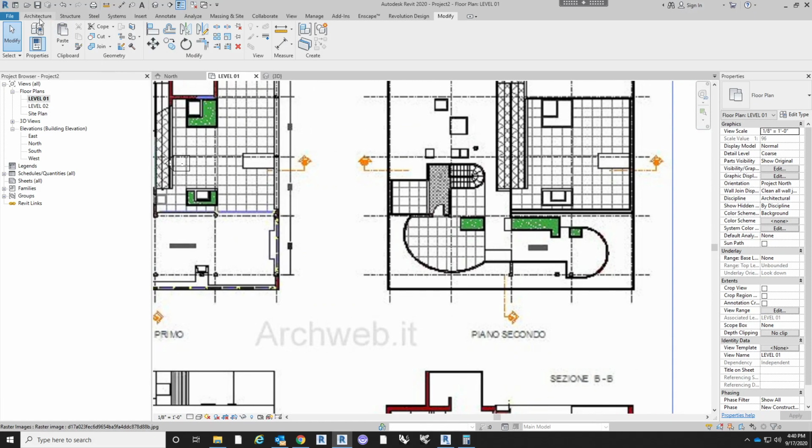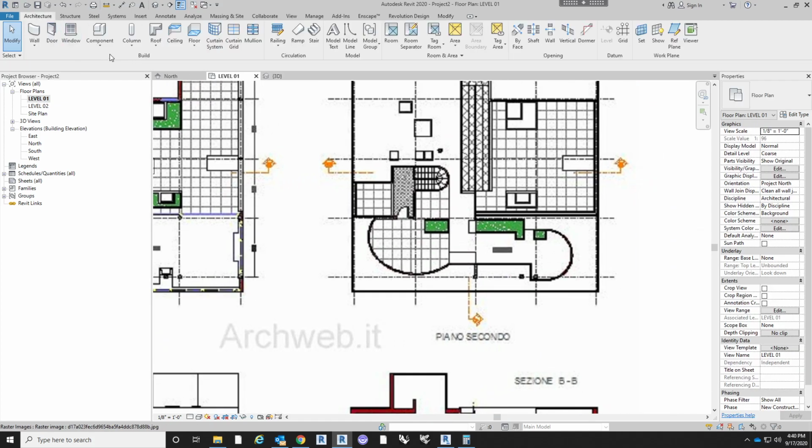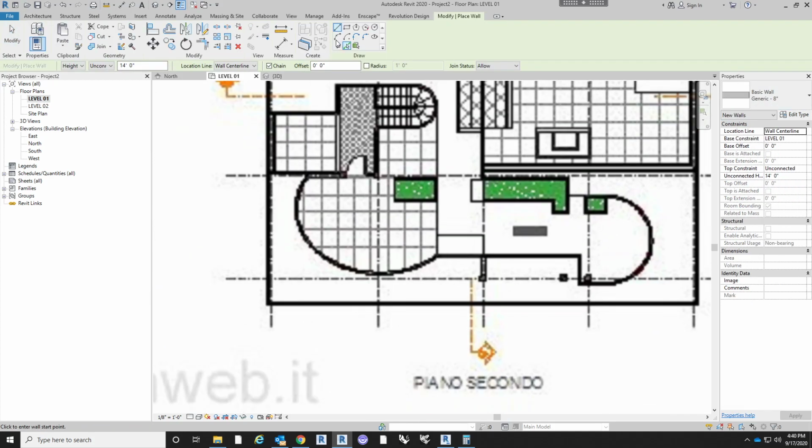So all you got to do for these curved walls on the roof terrace is go into a wall, select whatever wall you're going to end up using, and then I typically use just the start end radius arc, because these are all true circular radius.